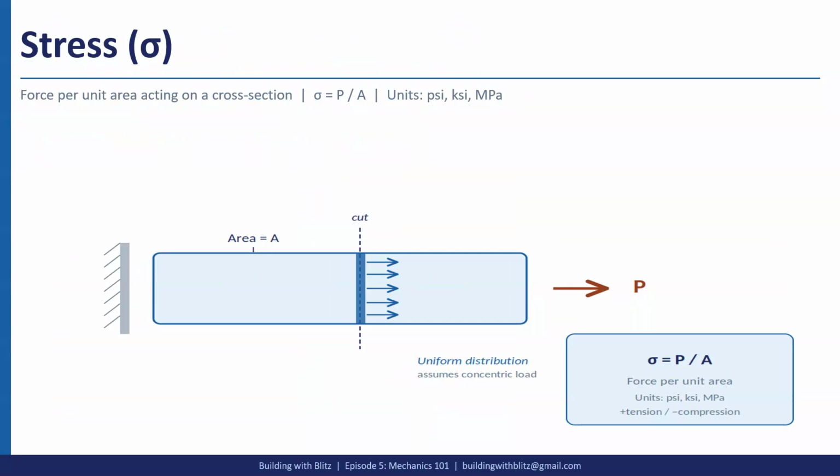There are several different types of stresses, which we'll go over today, but it should be noted that given that it's a force over an area, those units, if we're looking at metric, most of the time are going to be pascals, which is Newton per meter squared or millimeter squared, depending on what degree of unit we're looking at. And same with imperial, with pound per square inch, psi, or kip per square inch, which is again a force over an area.